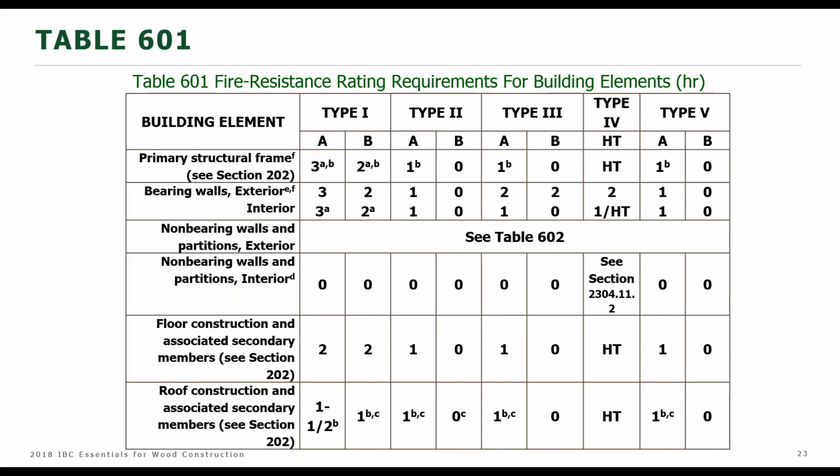I was talking about table 601. This is a primary location to define the construction types and to see what kind of fire resistance rating is required for each. I'm going to try to use this pen feature of my presenter capabilities here. This is kind of unusual. We mentioned there are no ratings here except for exterior walls, which are 2 ratings, but otherwise heavy timber dimensions. This is the construction type category that will be expanded with the new tall mass timber construction types.